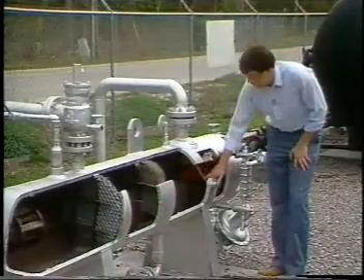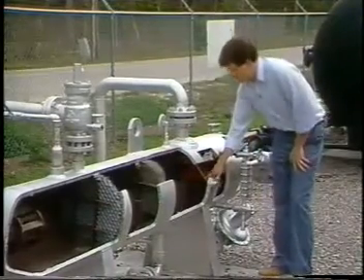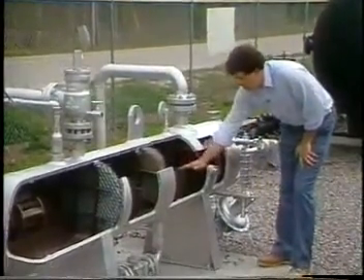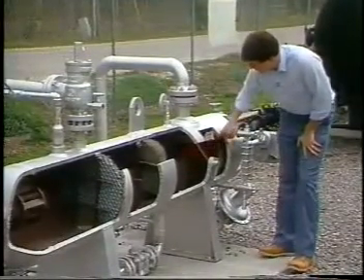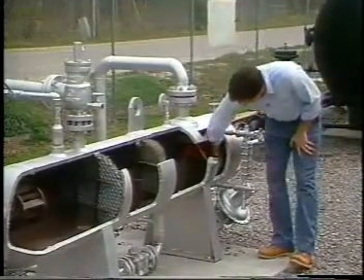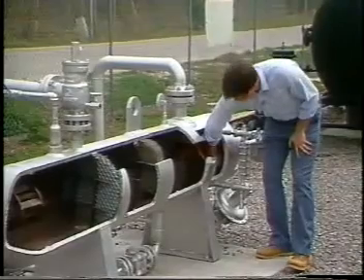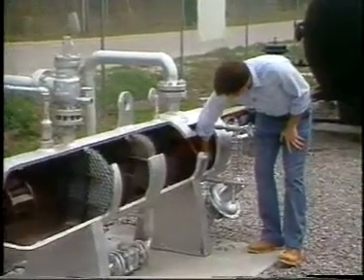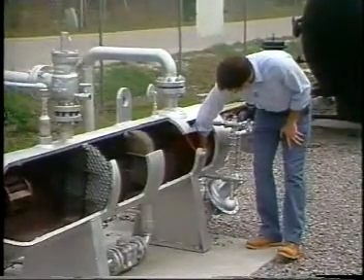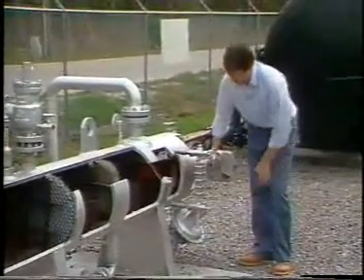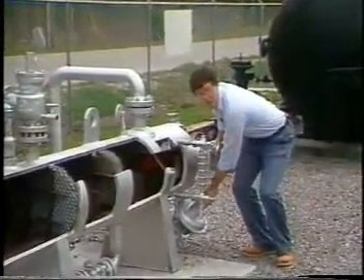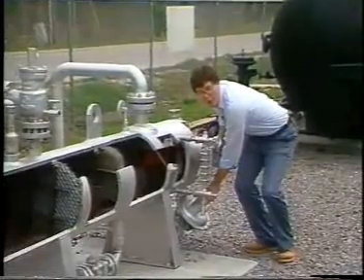We see here this weir which allows the oil on the top of the water to spill over into this bucket here, which is monitored by a float or a level displacer inside this bucket, which operates this controller, which operates this liquid dump valve down here for the oil phase.